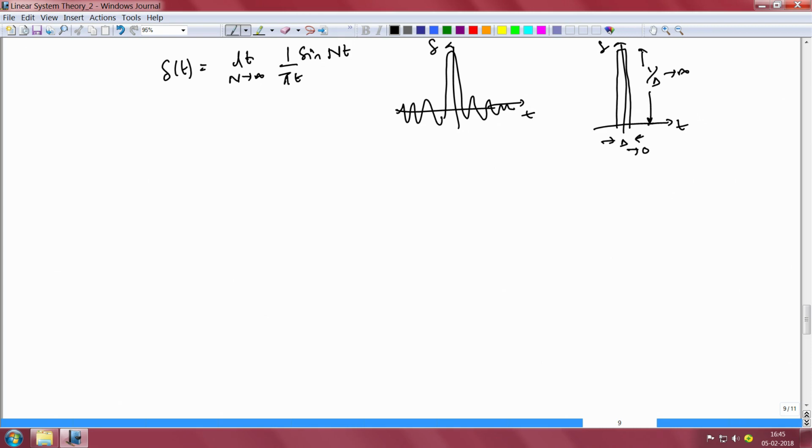Now let us apply a delta input on the right hand side of our system. Our system was x dot is equal to u, and u I have set as delta of t. Now why is this problem rather close to the homogeneous case? You see that in the case of a delta function, the input exists only for a very brief amount of time in the neighborhood of time t equal to 0. Before that there was no input, after that there is no input, which means that except for that small duration of time in the neighborhood of time t equal to 0, our system looks like a homogeneous system where you have no input on the right hand side. It is only in the neighborhood of time t equal to 0 that there is any input, and all we need to look at is how the input in the neighborhood of time t equal to 0 changes our response.